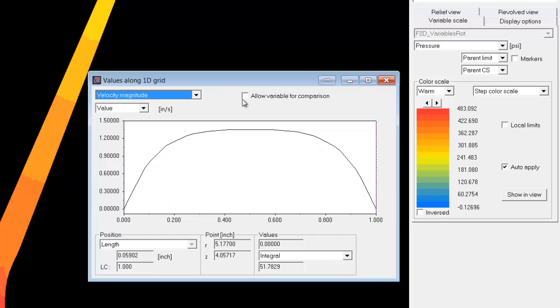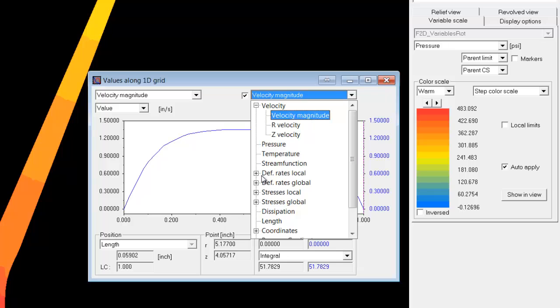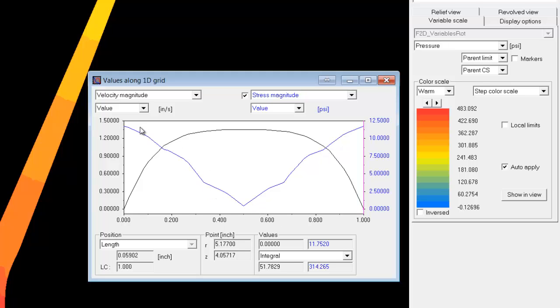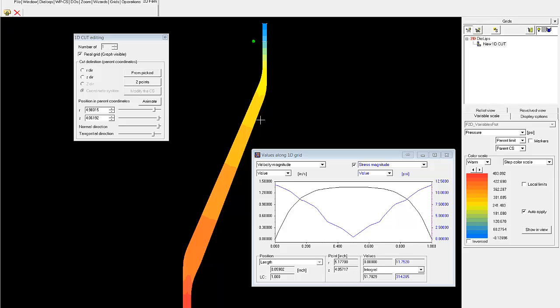And in fact, even if we add the stress on this graph, we see again that the stress is much more symmetric in this geometry. That's still a little bit, it should be a straight line, still a bit of fluctuation. Perhaps if we had a few more elements across that gap, this would be a little bit smoother. But that's how we import a DXF file and create a mesh, and generally recommend a hybrid mesh with a structured mesh in the small gap regions, perhaps even on the inlets. We should have a structured mesh, and then a random mesh in the larger areas.